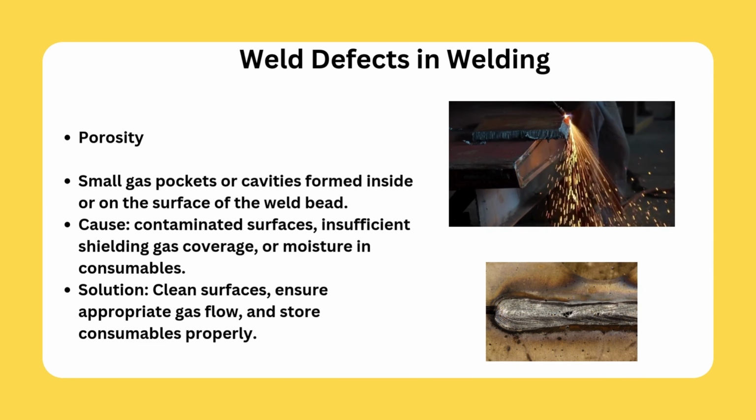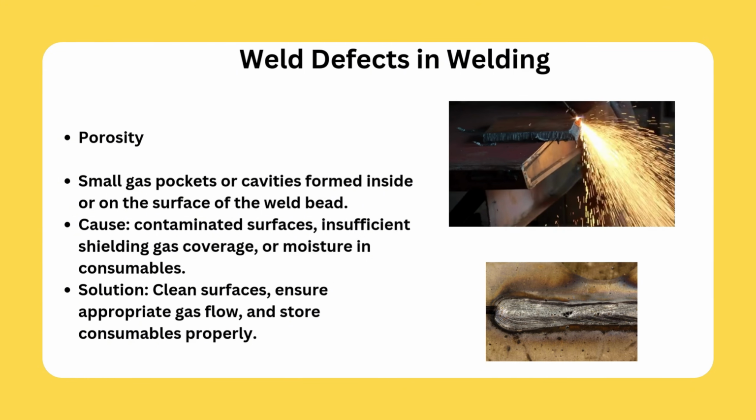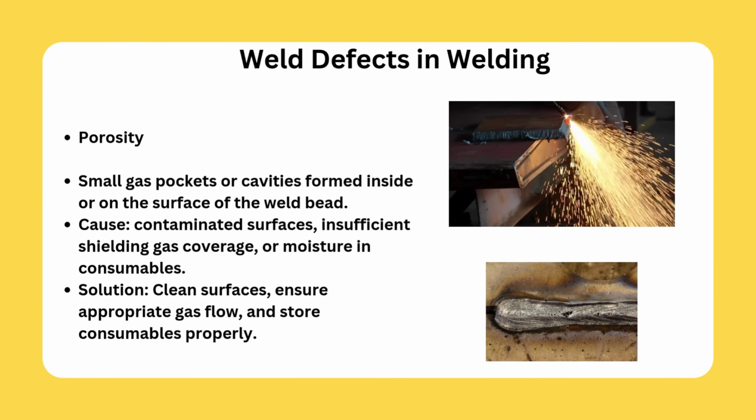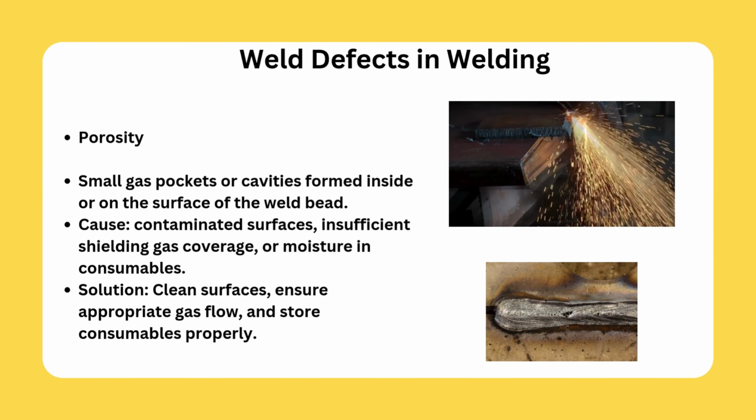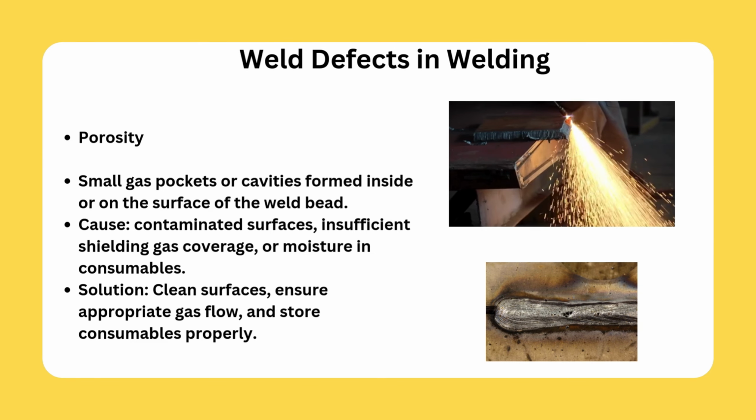Cause: contaminated surfaces, insufficient shielding gas coverage, or moisture in consumables. Solution: clean surfaces, ensure appropriate gas flow, and store consumables properly.